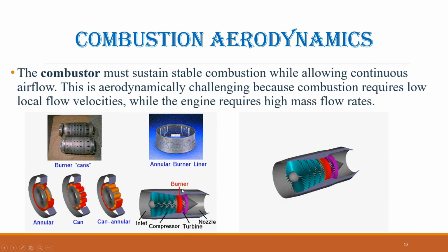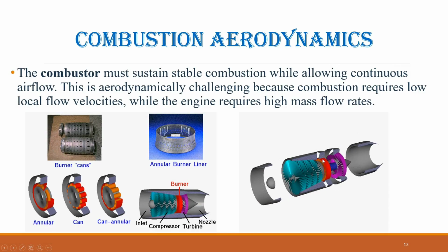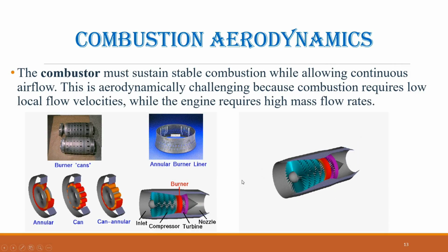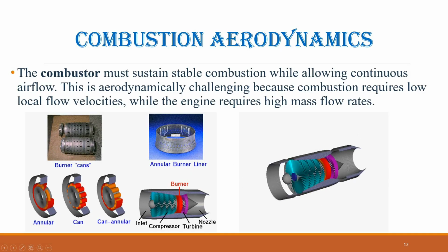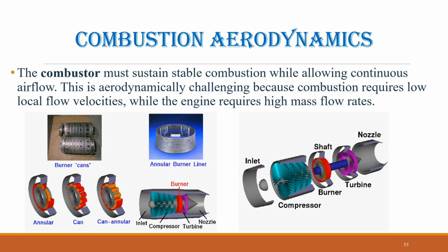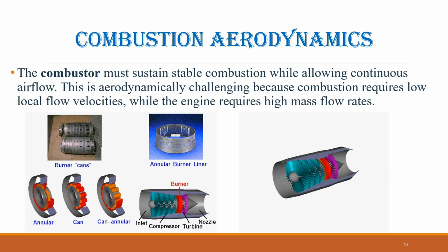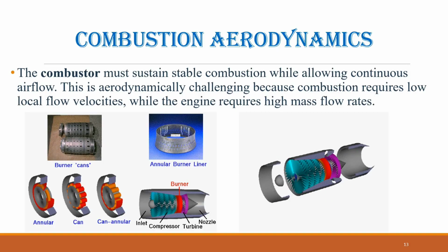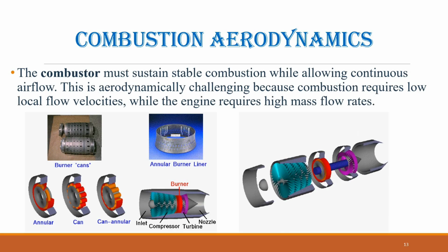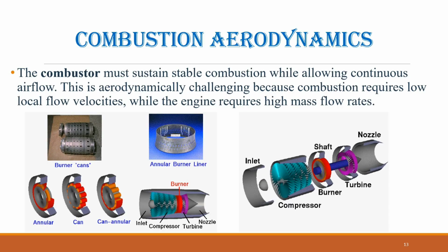Combustion aerodynamics. The combustor must sustain stable combustion while allowing continuous airflow. This is aerodynamically challenging because combustion requires low local flow velocities, while the engine requires high mass flow rates. This problem is solved by creating recirculation zones inside the combustor. These zones trap hot gases and act as a continuous ignition source for incoming fuel-air mixtures.